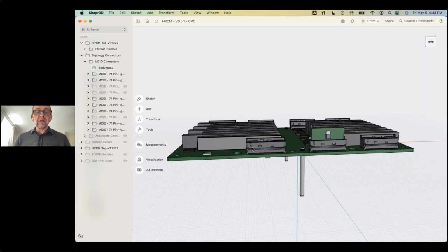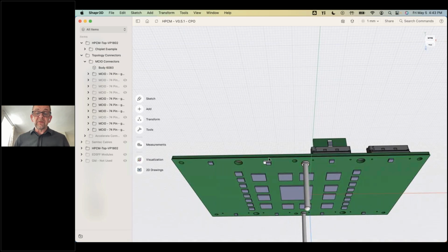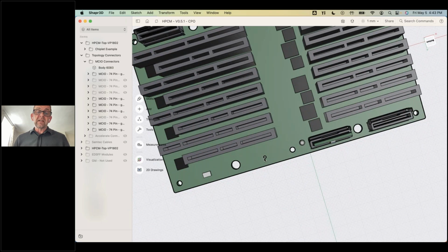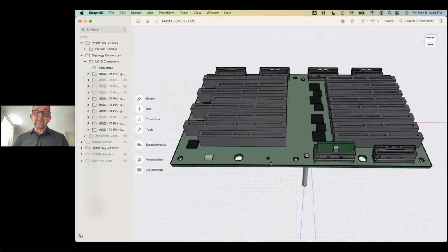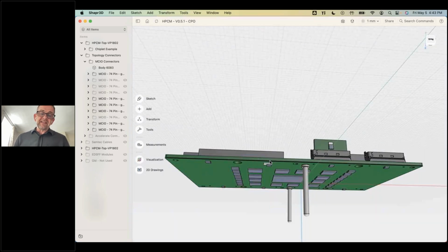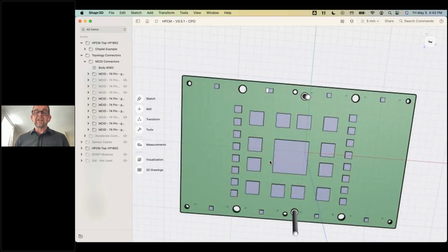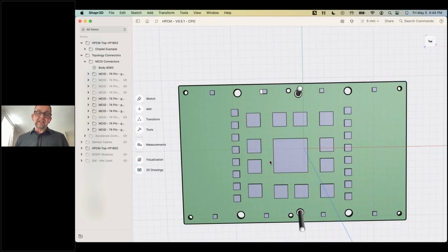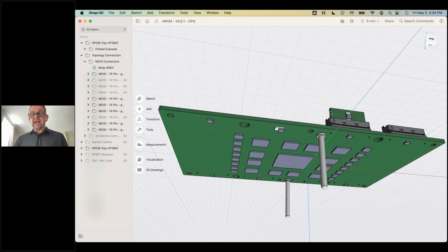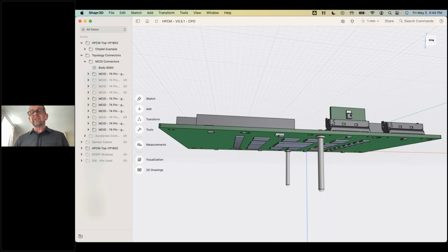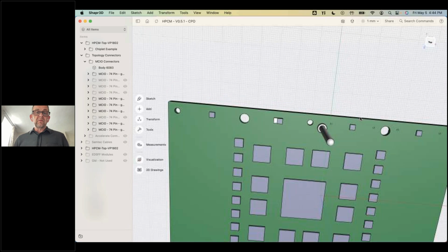And then on this other one, if I just hide this one as well. Here we've got them on this side of the board, and we've just got a hole through the board with the optics coming through it here. So that could then drive into a passive optical cable. I mean, this is very cartoony, but the idea is we can start to introduce optics, and we don't have to go all the way to co-packaged optics. It might be easier to go to this near packaged optics, and this could be a half a picojoule per bit interface, maybe. If you've got picojoule per bit optics, then that's quite a low power optical cable that could go up and down the data center. So that's that.